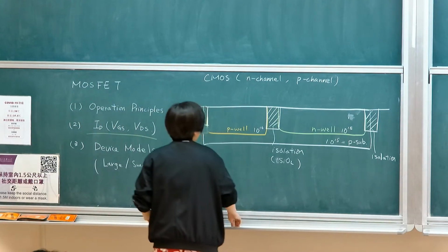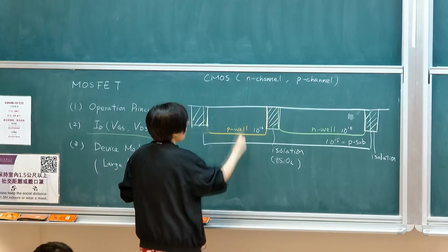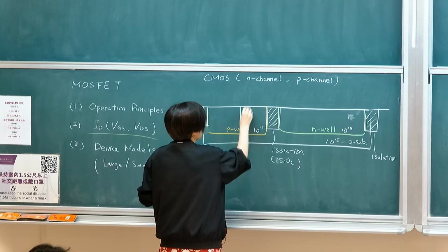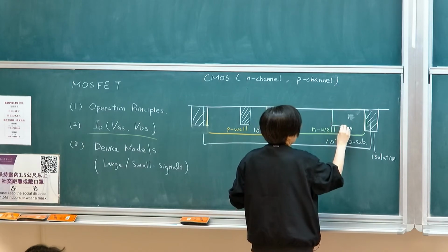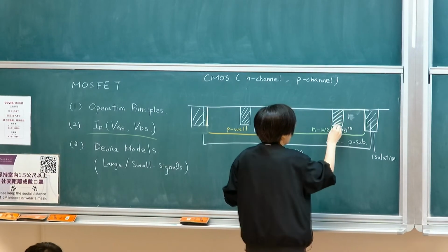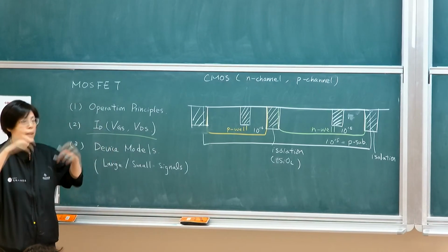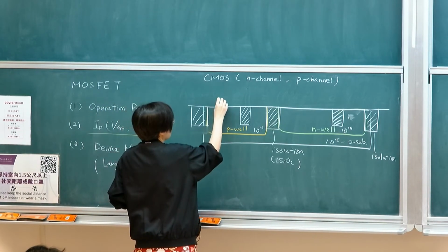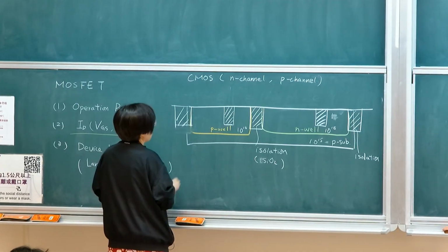And then what is typically done is that I want to make my transistors. So I do the isolations, and maybe internally there might be some isolations here. I just want to show some isolation. This is just to isolate the implants on top, the pickups. And then we're going to make our transistors. When you make the transistors, we need a metal oxide structure on top.